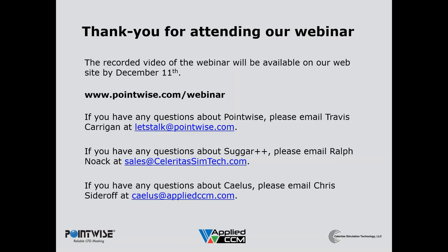If the bodies are in contact, Suggar++ supports the identification of cells that could be treated by an appropriate solver using an immersed boundary method. So it's a way of doing things without a collar, but you would have to have that kind of immersed boundary method capability in your solver to approximate the geometry that's defined in one grid by cells in the region in another mesh.